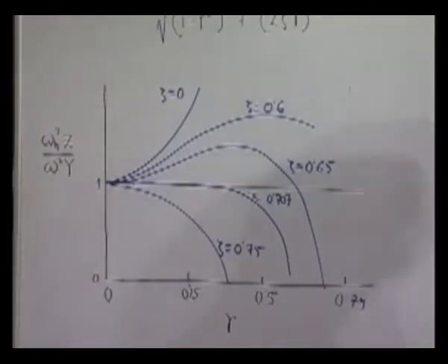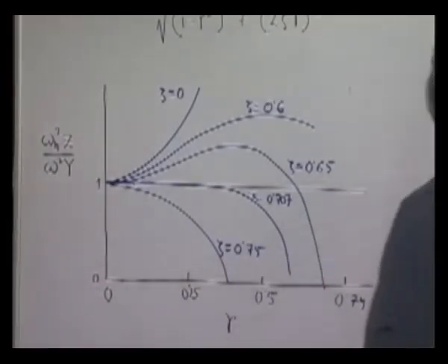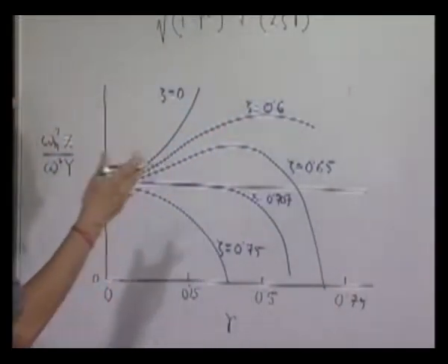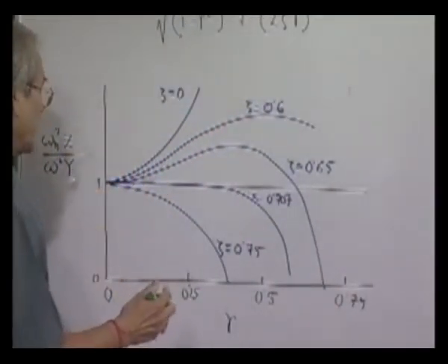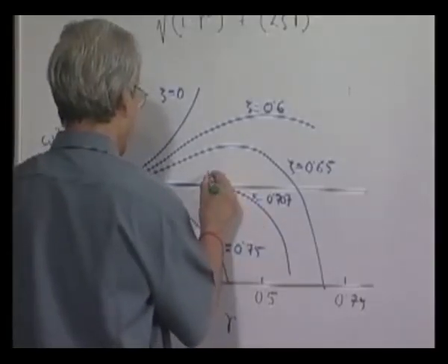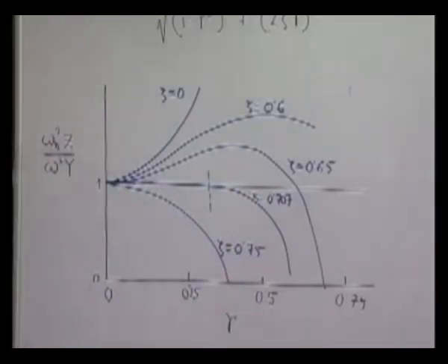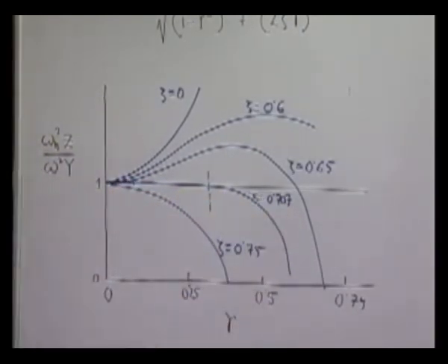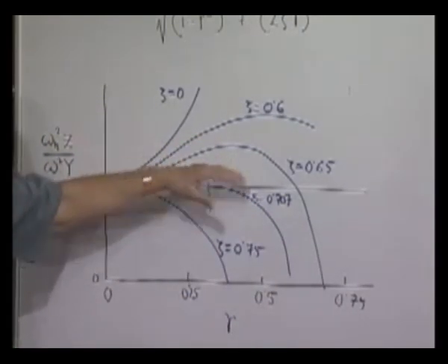when we plot the details, we can see now that of course our condition is that r has to be very small compared to 1. Again we should try to have as much range as possible, and we find the largest range when this relationship is approximately satisfied is obtained when zeta is equal to 0.707 compared to all other possible values.